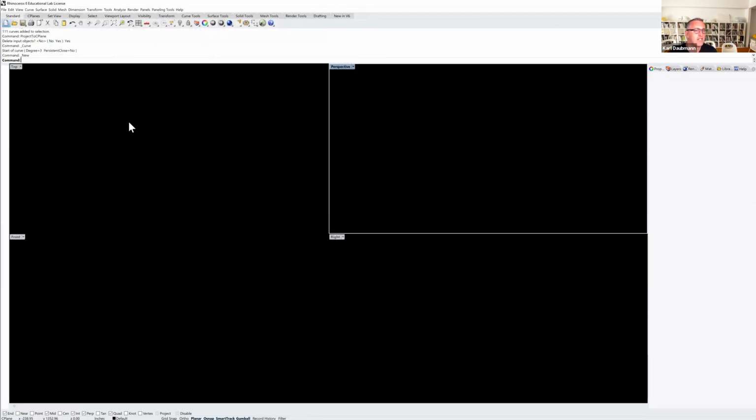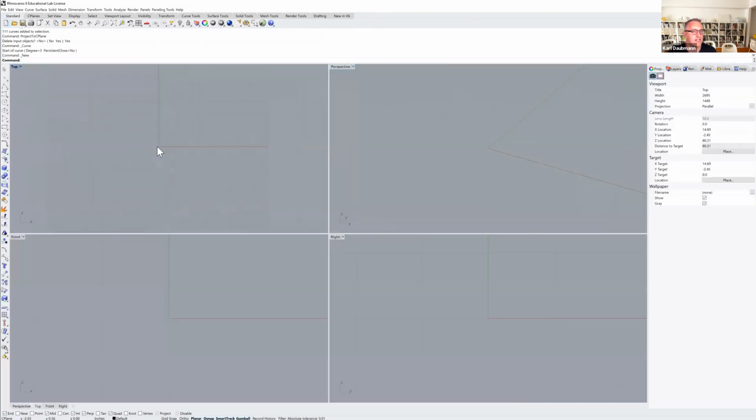Large objects, inches. This time, let's make the standard wobbly tower option. So rather than a topography where we're drawing an elevation and extruding it, we can draw 3 closed shapes in plan. In terms of closing the shape, you can either snap on the first point, or you can see there's an option up at the top. So you can just type C and enter, and it automatically closes it.